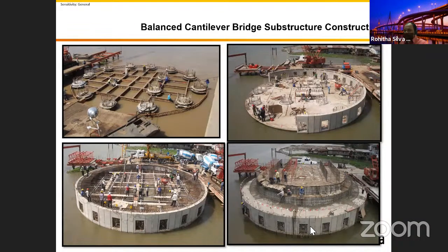The height of this footing is 4.5. You can't cast this footing in one go. So you have to cast that one in different stages, and to make sure that the heat of hydration is not going to make a lot of cracks. In addition to that, this one got a lot of pre-tensions inside. And these are massive mega structures you're going to build.